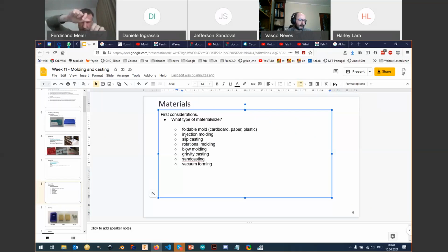They already have the thread and everything on top. Those are made in injection molding, and then you stick them into a mold that on the inside has the shape of your finished bottle. The whole thing is heated, and then you blow compressed air inside, and the thing will inflate like a balloon and catch the outer shape of the mold, and that's blow molding.